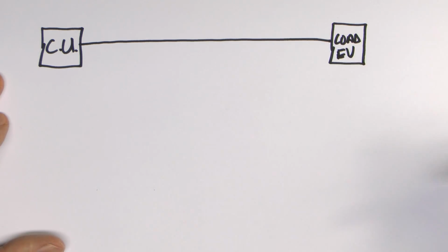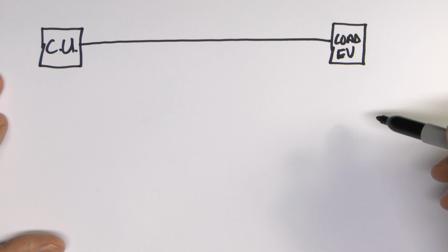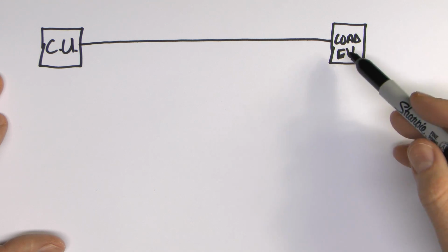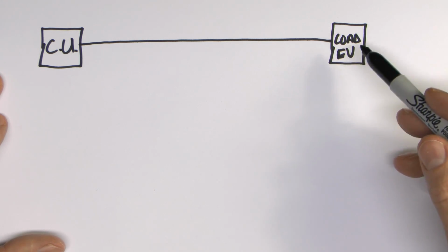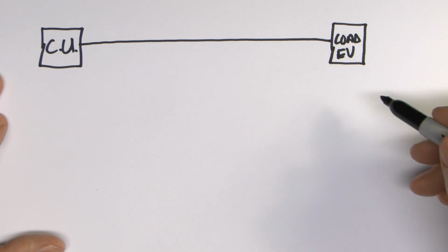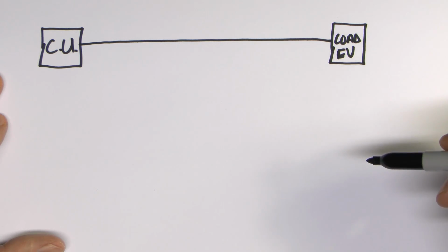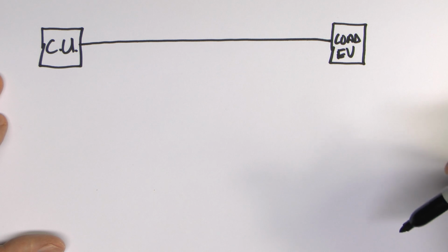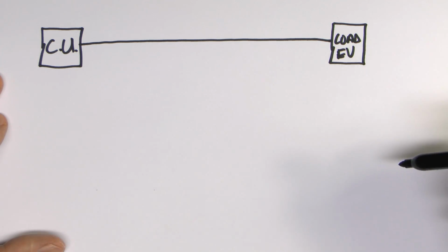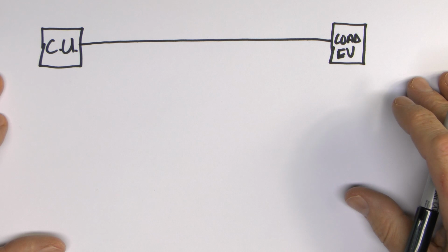And the reason we're choosing this is because an electric vehicle charger is going to be on for an extended time, typically many hours at a time, and it's also going to be of a decent loading, typically in the range of either 3.5 or 7 kilowatts. And though you could do this for any circuit in the house, the reality is that for most domestic circuits at least,